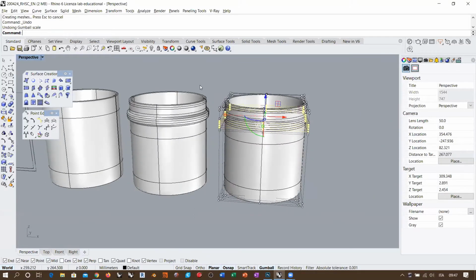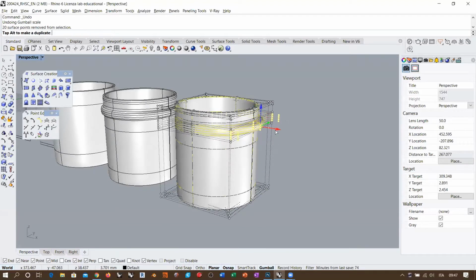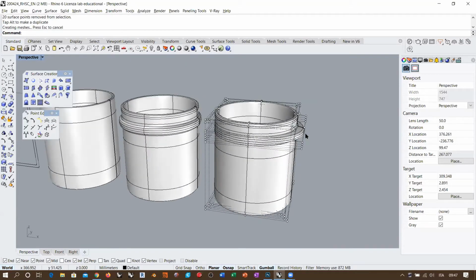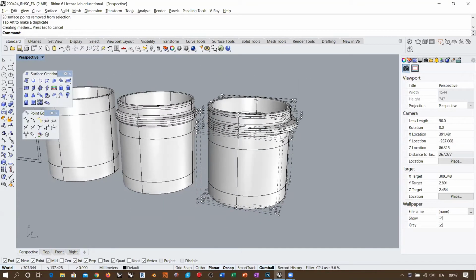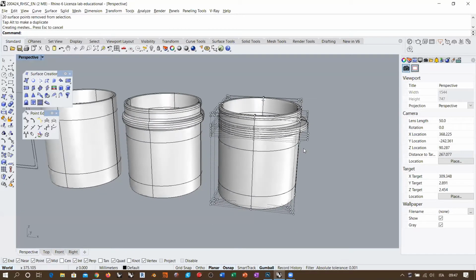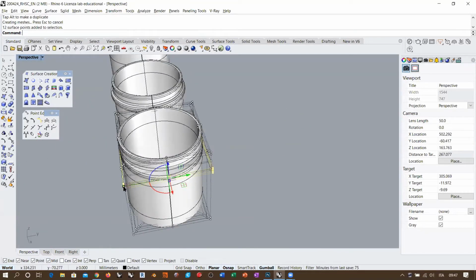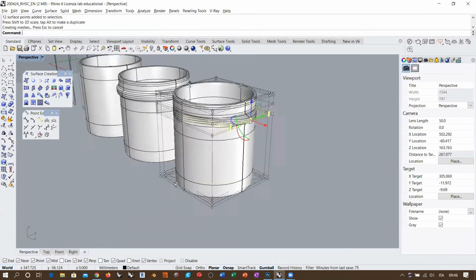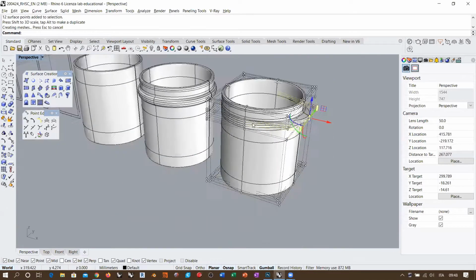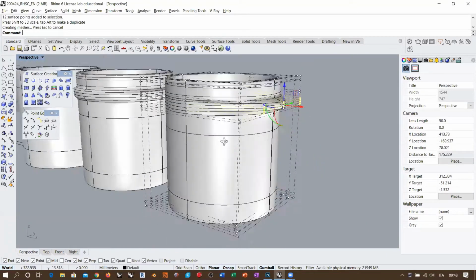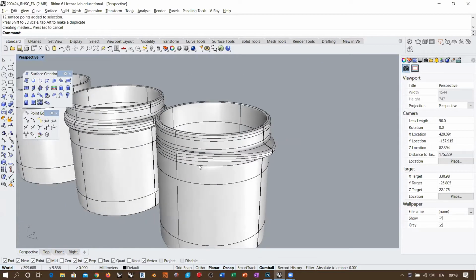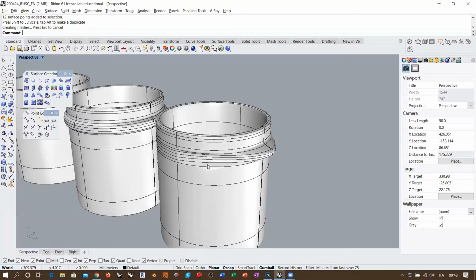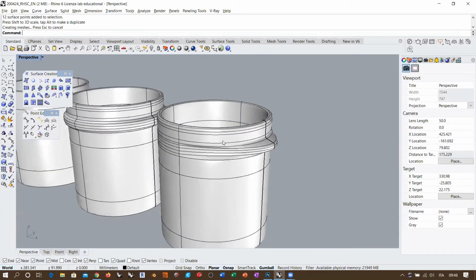So for example, what I'm saying is that I can eventually do something like this. So a deformation that happens only on one side of the glass without creating any discontinuity, because I'm not breaking the circle rule. But I cannot do this, for example, if I want this thing to be narrower, like this. I cannot do this because now I am creating a crease here. Now, can or cannot do depends on what we want to achieve. Of course, this object is still a valid object, okay? But it's not smooth. So normally we tend to create some deformation that doesn't break the smoothness of a surface, okay?